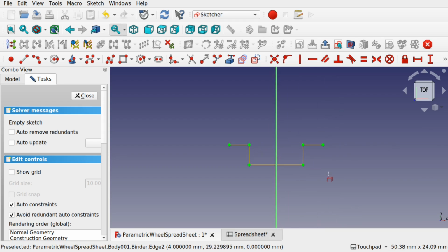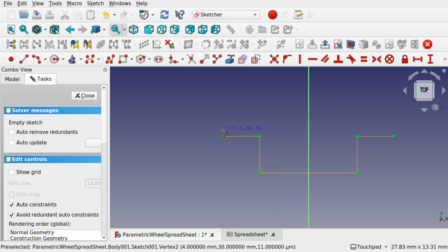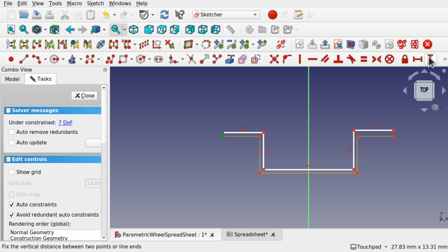Now we're going to start creating the tyre. For that, I'm going to use a polyline, and it may be worth thinking about tolerances here when you're creating this tyre, because it's got to fit on top of this one, and if we trace this line exactly, then we may get into problems. What we need to do is add a bit of tolerance in here, say coming out here and pulling this line all the way down and across. Hit escape, escape again, and then we use some height between these two